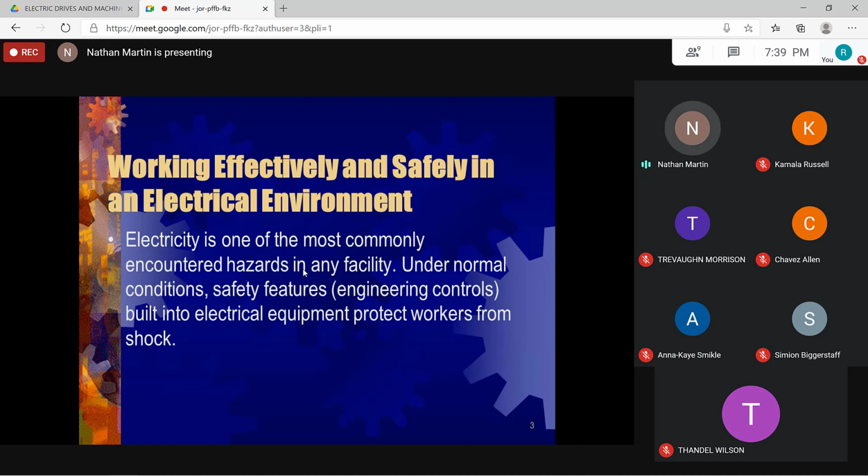Right? So my advice to that individual was actually to pull the one-bolt clamp, right? Clean up the one-bolt clamp, get a little grease, put it back, apply it to the one-bolt clamp and make the connection. At the end of that process, the customer said everything is fine now in the panel, right? So experience teaches a lot, right? And that is one of the reasons I love this module, right? It helps me to bring my experience in the field to the students in the classroom.